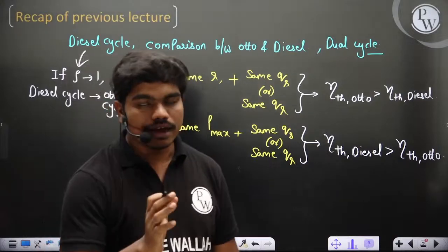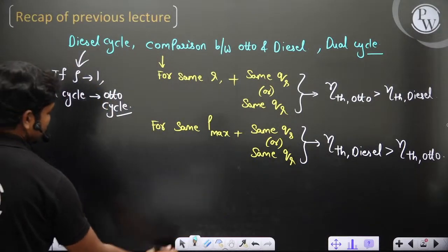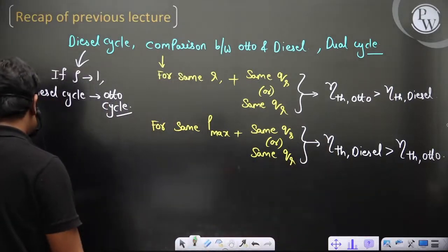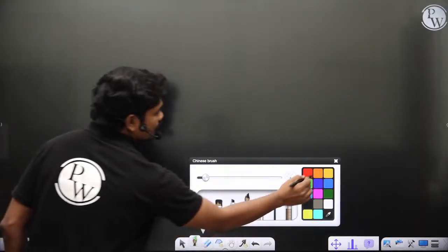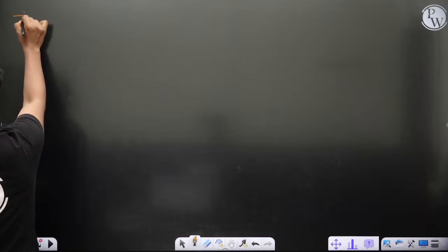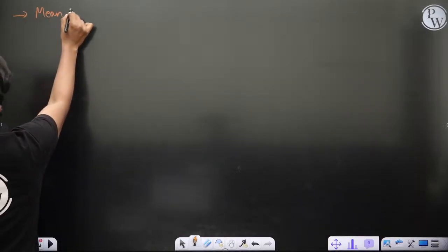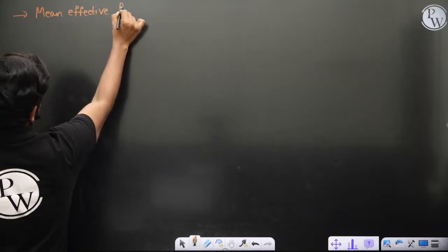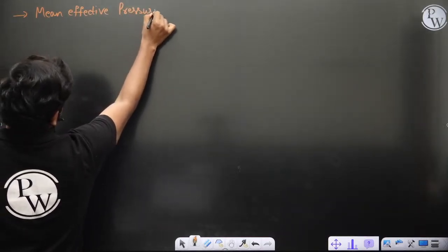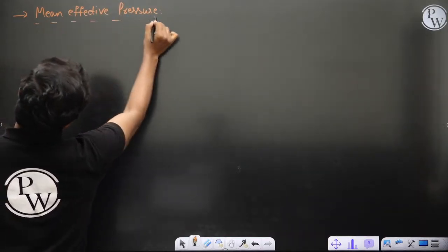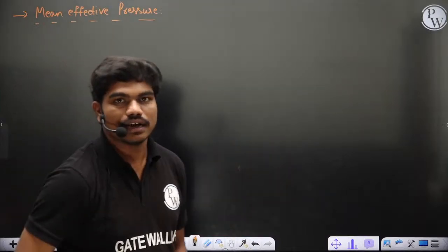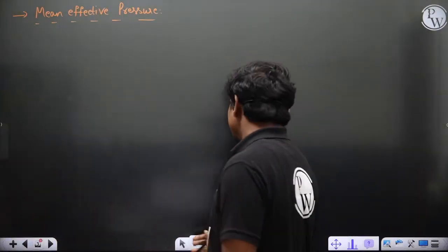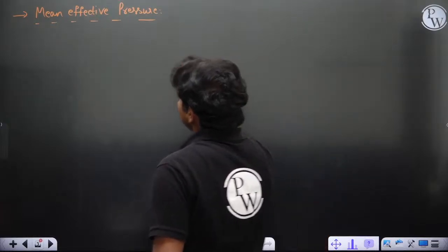Now one important thing here is, I just forgot to tell you, because in solving some problems in yesterday's class, we define something called mean effective pressure, which is actually important in engine calculations. Similarly, something similar to this we will also calculate in Rankine cycles, which is called mean temperature of heat addition. So first let us see what is this mean effective pressure.